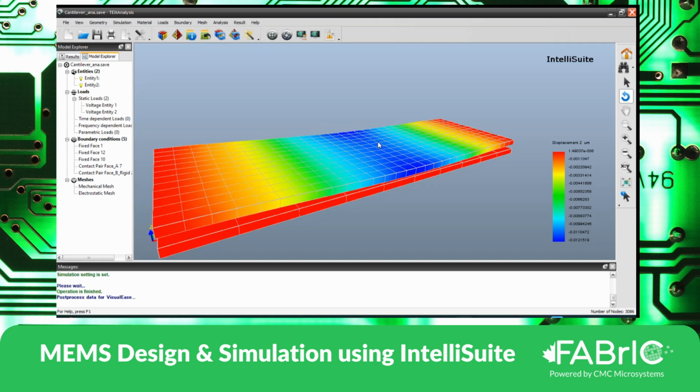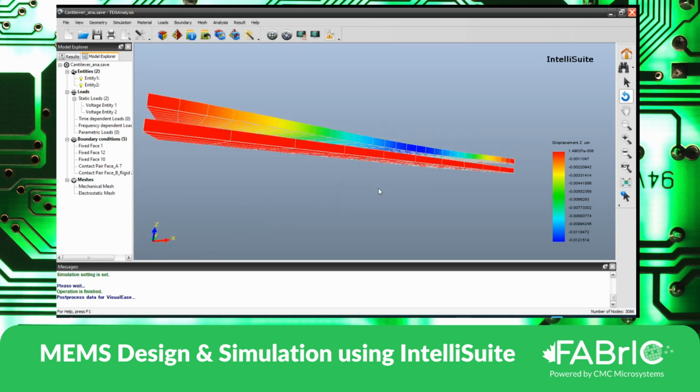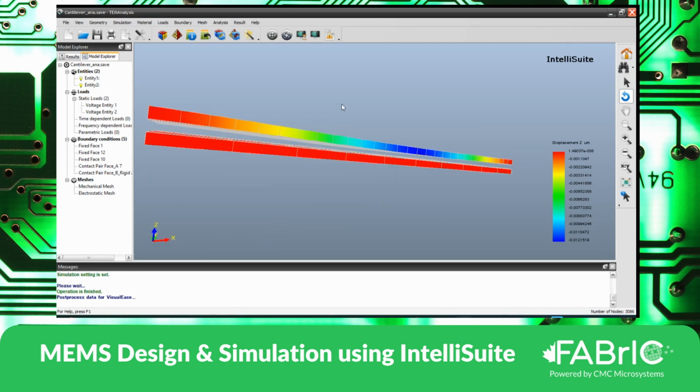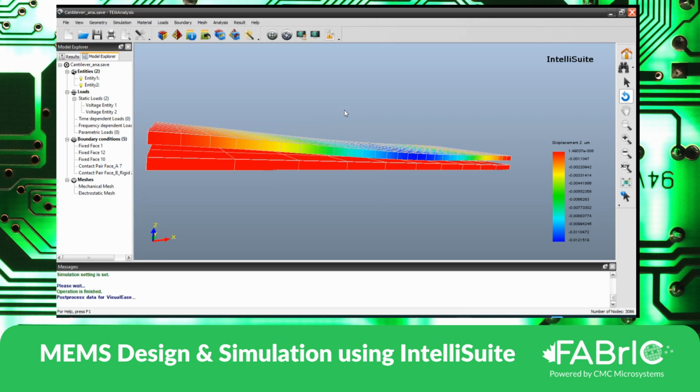By default, does it take air as the dielectric material? Yes. So one has to make the same box and define air as a dielectric? No, he did not draw any box in this case. But regarding that question, if someone has to define it, they have to make the box with the same dimension and define the material property as an air dielectric.